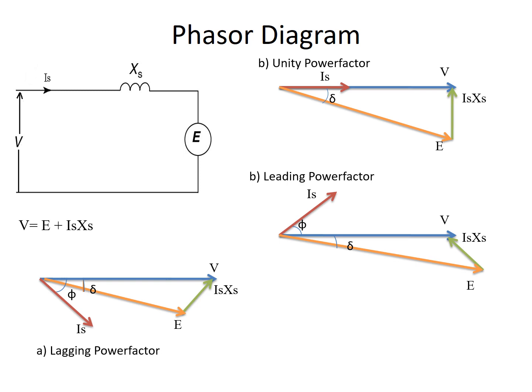So when excitation is small, the machine operates in lagging power factor. If you observe, when the excitation EMF E is small, the machine operates in lagging power factor, and the power factor can be made unity or leading by increasing the field excitation. So the important feature of wound field motor is that its power factor can be controlled by varying the field current or E.